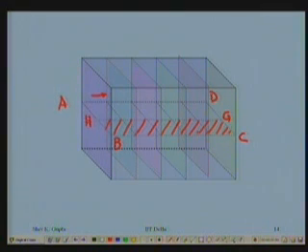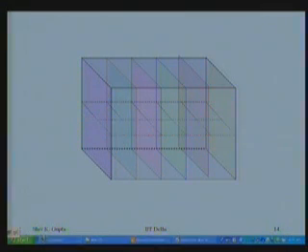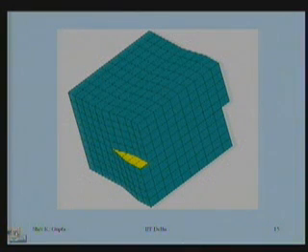What happens? We get a configuration like this. I tilted it to show you what is going to happen here. It's up to here I have cut the bonds. Beyond that the bonds are not cut, so this atom here is bonded to that atom without problem. But this bond is cut, so this is pushed. But it cannot be pushed as much as the front one can be pushed. So I have been able to push this by almost one interplanar spacing, while these go a fractional distance, because this one doesn't move at all, because the bond is not cut there.